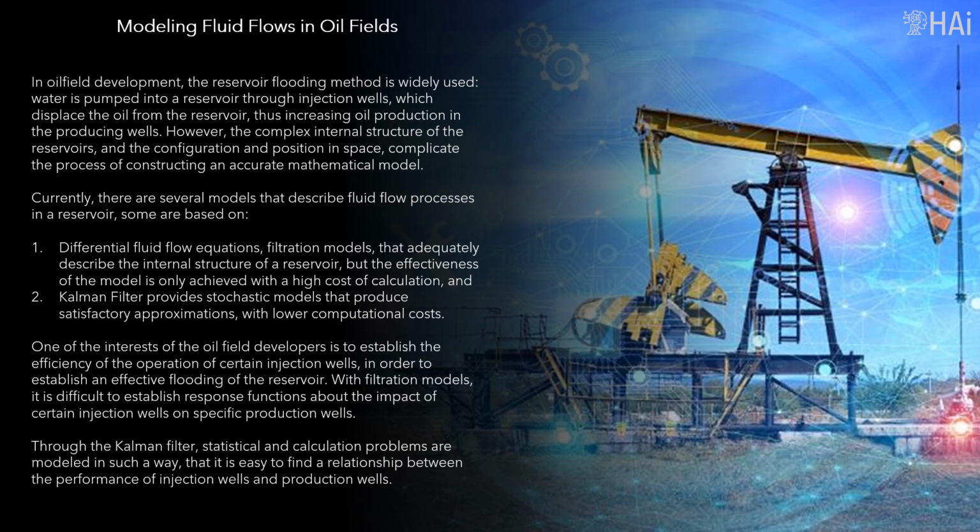One of the interests of the oilfield developers is to establish the efficiency of the operation of certain injection wells, to establish an effective flooding of the reservoir. With filtration models, it is difficult to establish response functions about the impact of certain injection wells on specific production wells. Through the Kalman filter, statistical and calculation problems are modeled in such a way that it is easy to find a relationship between the performance of injection wells and production wells.